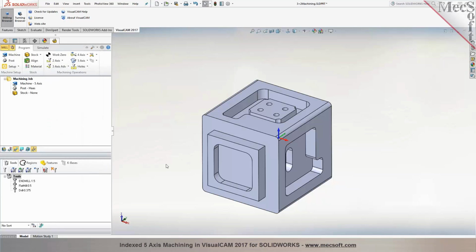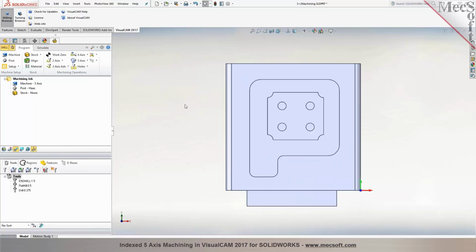Yes. All right, so now here we're going to go back and reset it to the world coordinate system, the same orientation. So when we want to start machining this part, we're going to basically place the block so that this feature will be looking down through the machine tool as you want to mill this. So you have your X, Y, and Z orientation, and the origin is over at this corner. Now we've established that.